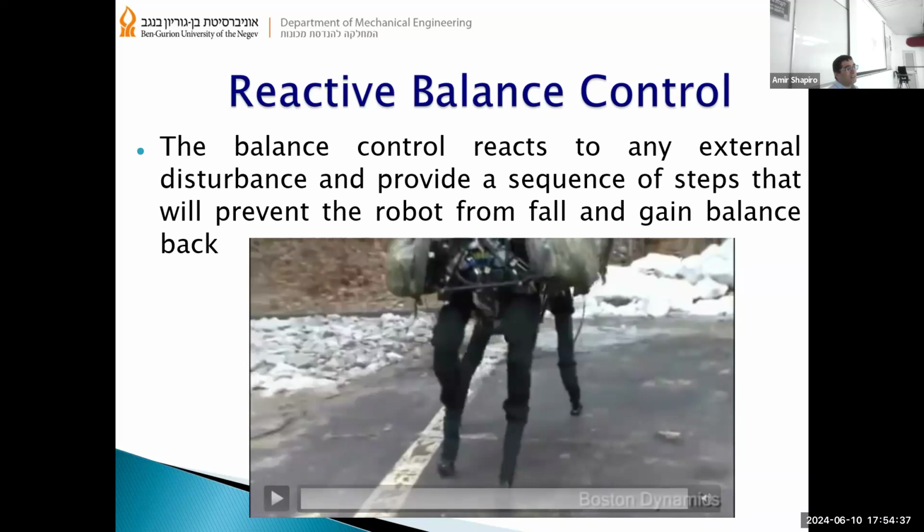Very impressive what has come in the models since then, because you see Spot walking, the latest version. You don't steer the motors at all, you steer the steps. They changed from hydraulic motors to electric motors, so it's very quiet. The electrical motors are direct drive, so there is no gear, and therefore you don't hear the gear.